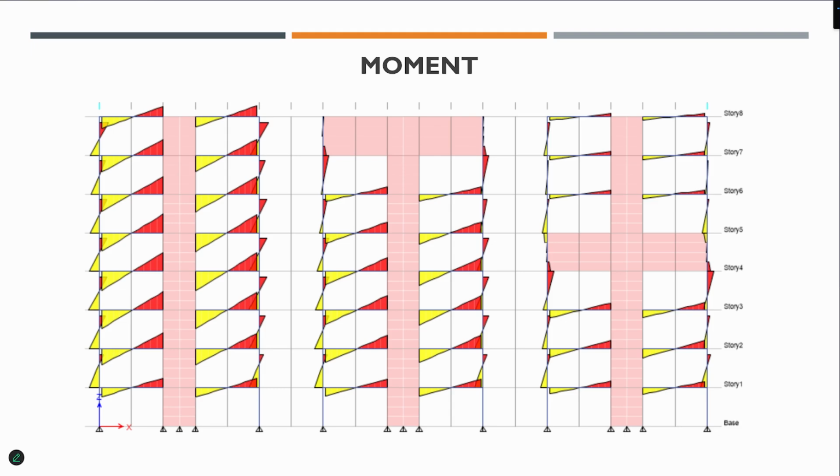That's why it is possible to have flat slab at each floor level. We don't need the beam anymore, and we put all the beams together at the outrigger. And that is the reason why the flat slab system with wall, with outrigger will work. Otherwise, it cannot work. That's exactly the way that we do that. We collect all the small beams together and make them a big beam and put them as an outrigger. Maybe 2 floors high. Imagine 2 floor high beam, 3 meter plus 3 meters, 6, 7 meter. 7 meter high beam. This is 3.2 meters. 7 meter high beam, imagine the stiffness of that thing.